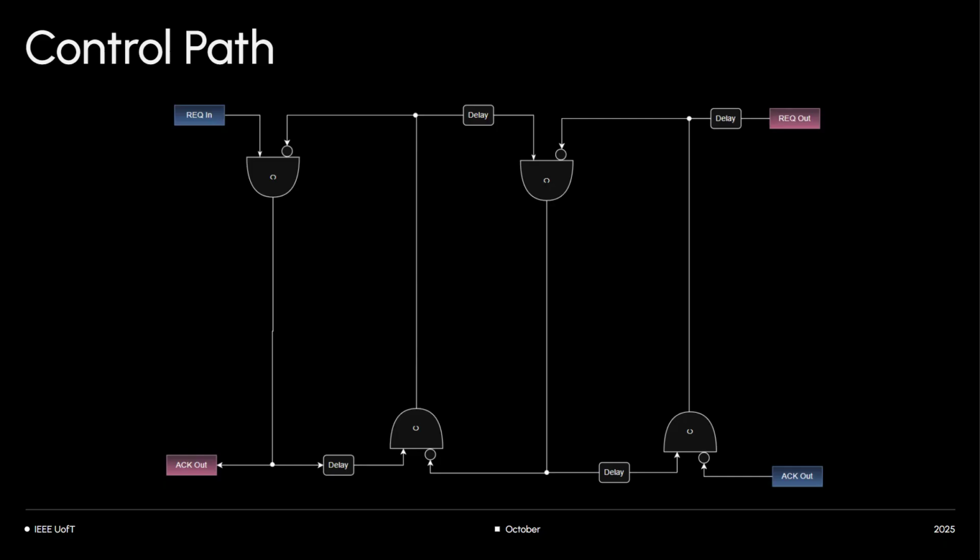Yeah, exactly. Because this acknowledge came through, it kind of cleared off this gate, so the 0 can get through. Same for all the other acknowledges. If you don't receive an acknowledge, it just blocks that particular stage from propagating any kind of control signals, any kind of request.